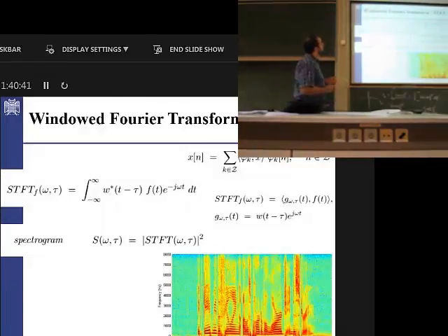For the windowed Fourier transform, we have the window sliding over the signal. And for the STFT, we take these atoms. They are also dual, if you want to know that. Let me first explain this. When we say the STFT transform of the signal, it means that if this is the signal f(t), you need an atom for the STFT. This atom is w(t minus tau) times e to the power of minus j omega t.